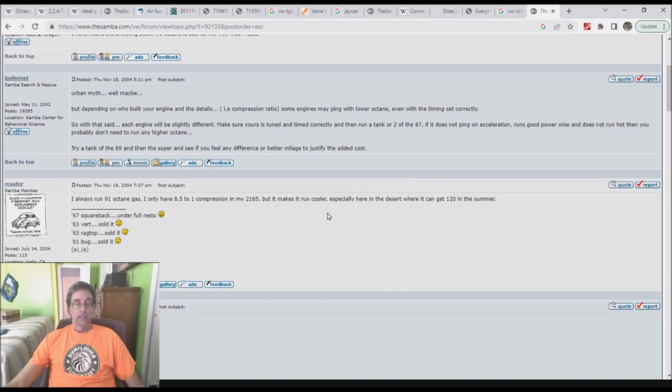So he's making the claim that the high octane stuff makes it run cooler, but he's actually done a back-to-back comparison between like an 87 and a 91, and he didn't alter his timing. It's not an apples to oranges, but he doesn't realize that he's not done a fair comparison. He released the same amount of heat. If you burn it properly with the proper timing, his motor should be right there. They should be the same.